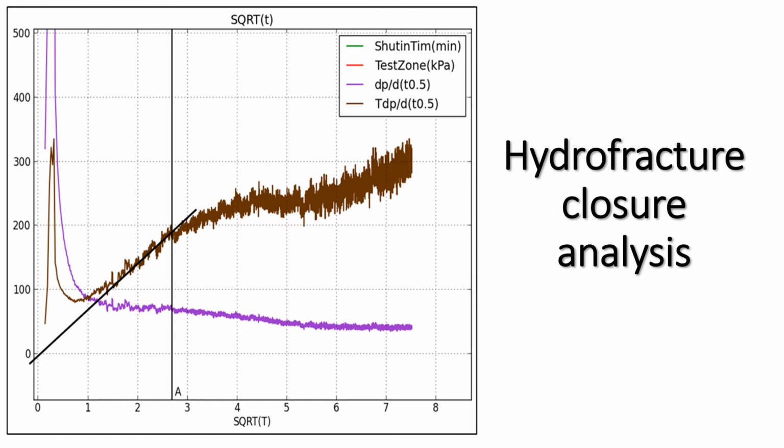The normal analysis of hydrofracture is based upon measuring the closure pressure of the fracture as an indication of the minimum stress level. This is determined by careful analysis of the pressure decline after pumping ceases. Frequently, several sequential fracture closures may be determined. These may be related to fracture rotation or pre-existing fractures within the rock mass closing in sequence.